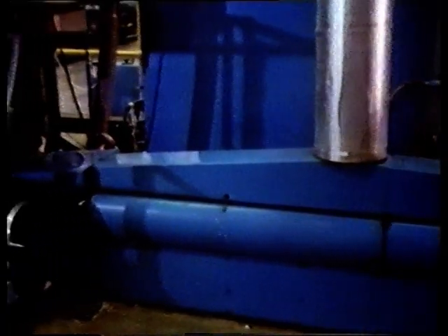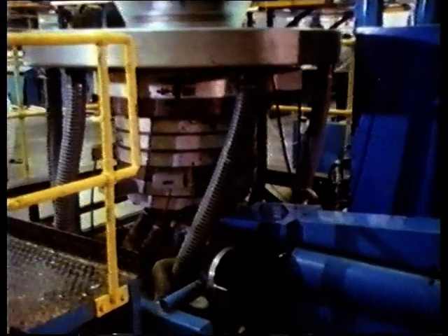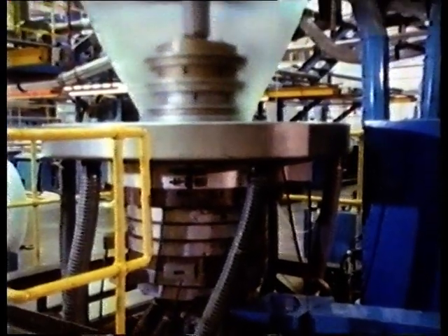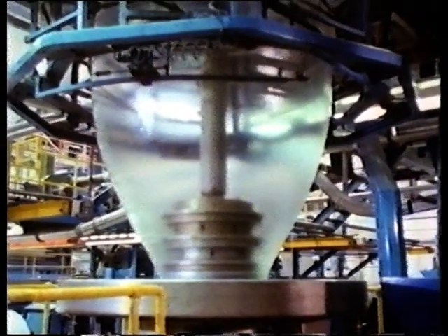The melted plastic is then forced up through a circular slot. Air is blown in the middle and on the outside, and this cools the polyethylene as it emerges, and a sort of huge bubble is produced. You can see the slots through which the air is blown in. Although it may look stationary, the bubble is continuously on the move upwards.